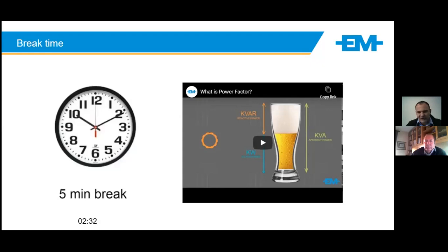Different vendors of variable speed drives have papers written about mitigation that will tell you to use this type of filter or inductor in line with the supply to the variable speed drive, and then also other mitigation parts on the output of the variable speed drive. Again, how much money you put into the variable speed drive will depend on the quality of what it does on the power network.